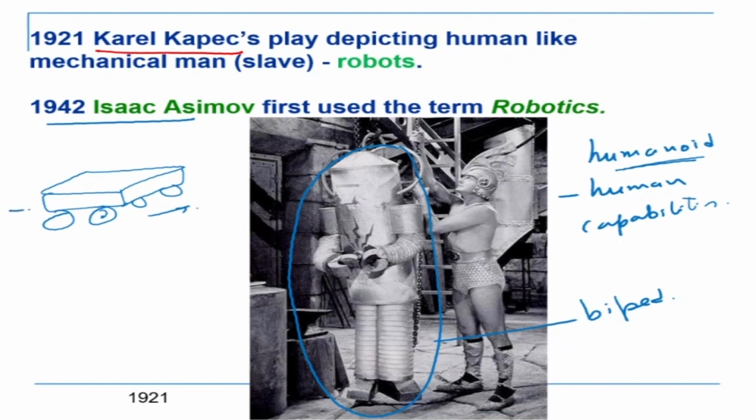Whereas if you talk about a biped, immediately you need what is called balance. That means a bipedal system is essentially unbalanced. It's a dynamically unbalanced system, and hence we have to balance it always. This would mean that it requires more energy, and it is more computationally expensive in terms of kinematics to get a biped robot to walk.